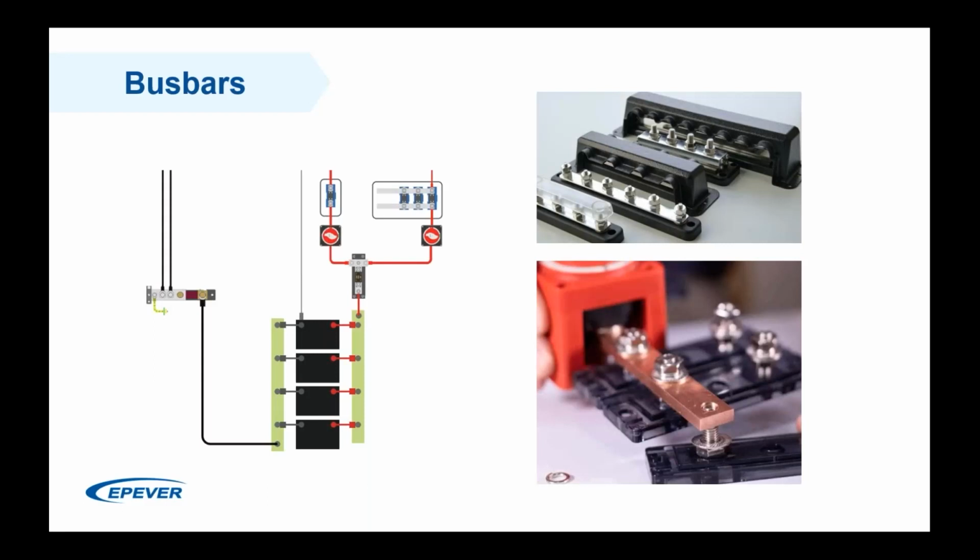Bus bars are like cables, only they are rigid metal bars. For convenience, some bus bars include fuse holders as well. So you can see there's a fuse holder, and they have connected some sort of fuses for each component that is going to be connected to the battery. In my case, for simplicity, I have one inverter, and I've used this terminal of the bus bar, which also has a fuse, to connect the batteries to my inverter.